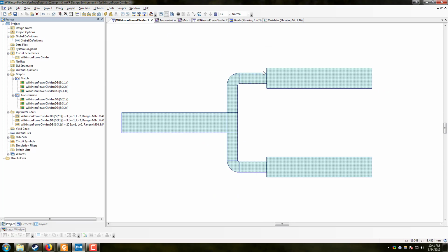Okay. So let's focus here for a second, actually. Between the quarter wavelength leg and the actual exit length, there's a pretty big jump in width. This is going to contribute to our mismatch as far as S11, S22, S33 are concerned. So what could we do here in order to help improve the match potentially? Again, we're basically going to establish a hypothesis, design an experiment, and go ahead and test our idea and see if it actually works.